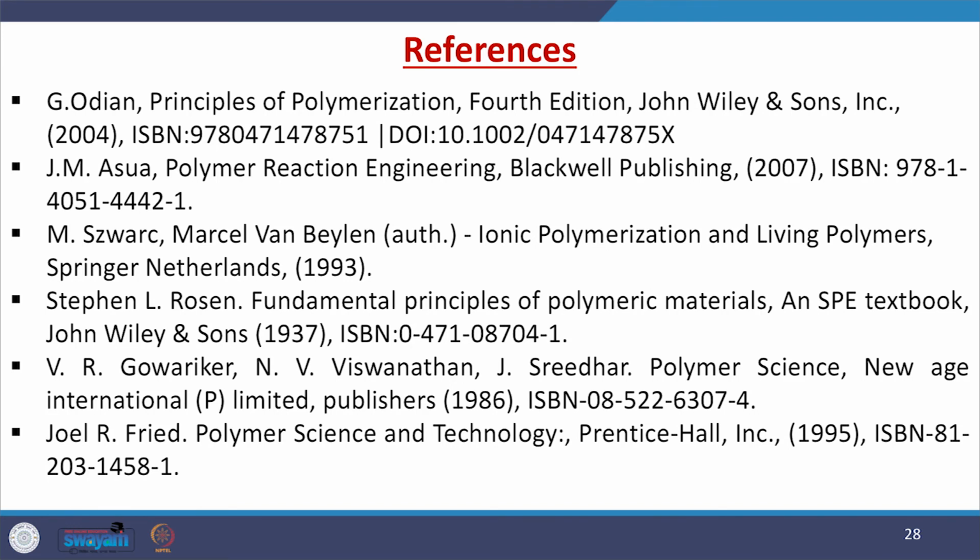So in this lecture, we have discussed the molecular weight distribution. We have discussed the efficacy of this molecular weight distribution to the polymeric system. We analyzed how we can determine this molecular weight, maybe number average, weight average, or viscosity average, mathematically, because there are several experimental tools available as on date through which you can determine these molecular weights.